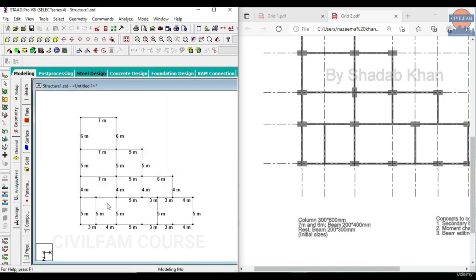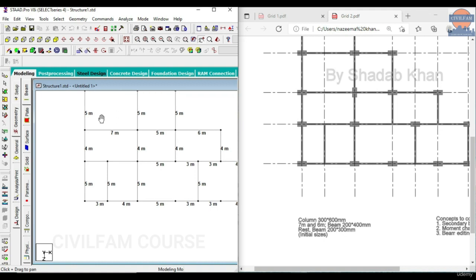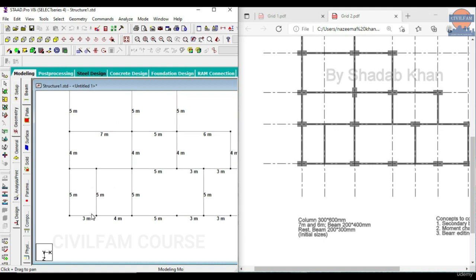Okay, now it is a single beam. Okay, now it is one single beam, but this beam is sitting on it. It looks like that. See, this is also not required, because in Staad Pro, when you are seeing your bending moment and shear force values, it becomes a bit tricky, but you can do it. Whatever value you're getting at this end, whatever value you're getting at this end, you have to add them up. You can do that.